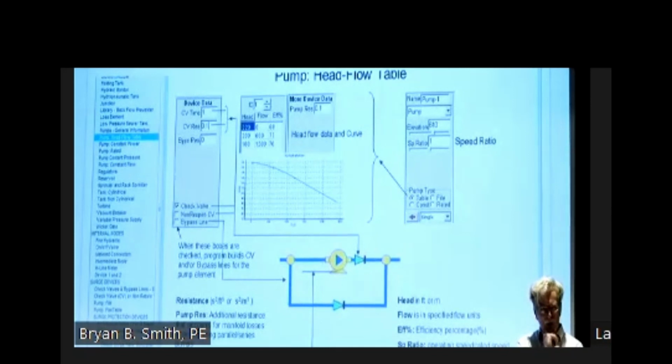The building goes, the piping, boom, boom, boom. This system's been working fine for 50 years. What's going on? Old pumps are great. Lots of inertia. Like at the New Orleans Sewage and Water Board, those old pumps are gorgeous, right? Heavy duty impeller, lots of inertia. The new pump, why does it weigh half of the old pump? No inertia. The old school design, they were thinking of inertia. They built the flywheel into the pump.